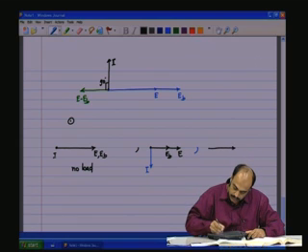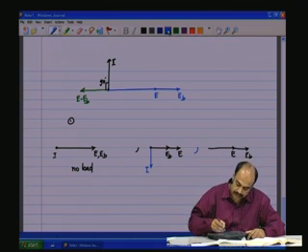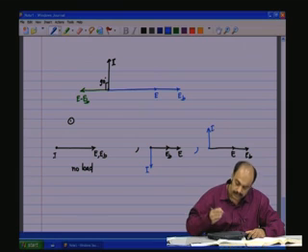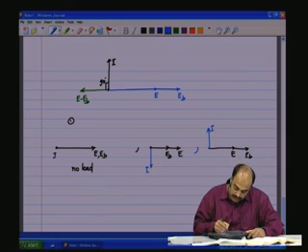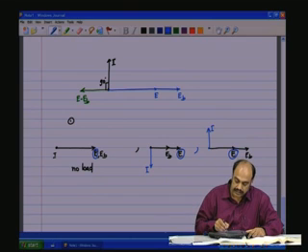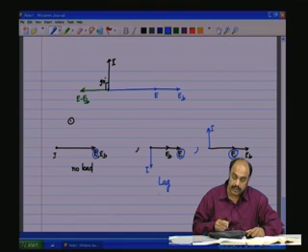And we have the third situation where we have E and EB is more than E, and as a result E minus EB is negative and the current is going like that. So with respect to E, that is the input voltage, if you compare the input voltage and input current, you see that here the input current is lagging the input voltage.